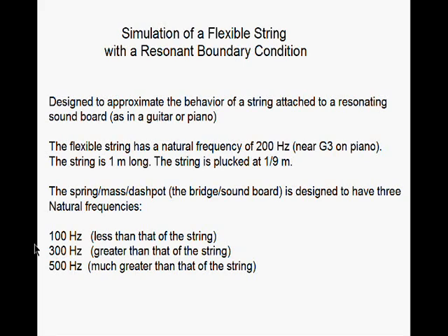The bridge in the soundboard is going to be simulated by a spring mass dashpot combination, and we're going to have 3 different natural frequencies for that spring mass dashpot. One that's less than that of the string, one that's greater, and the other is also greater.